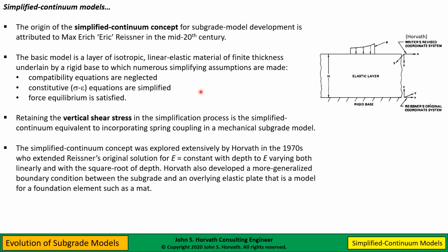The simplified continuum concept was really the heart of my doctoral research and dissertation in the 1970s. I started with Reissner's original solution. I did change the coordinate axes to be more geotechnical in nature. He only solved for a Young's modulus that was constant with depth. I developed a solution for Young's modulus that varied linearly with depth, allowing for an initial value, as well as one that varied as the square root of depth, allowing for an initial value.